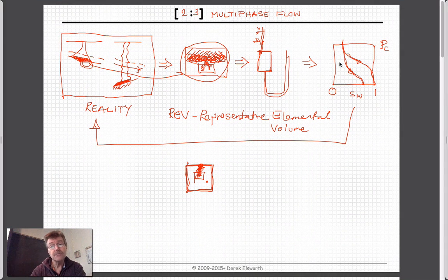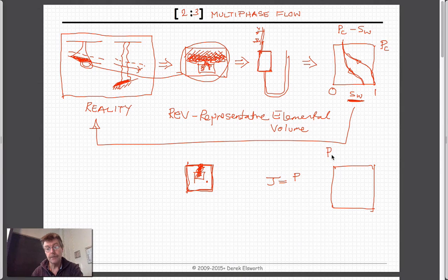So since this represents these behaviors, it seems reasonable to think that if we have this information in a capillary pressure versus saturation curve, then we should be able to use that, maybe, if we know what this is, to say something about what happens in situ. And the final part that puts this together is that we can also scale this in a certain way, very important, to these Leverett curves, which give us the capillary pressure, which I suppose we might define as always the difference between the non-wetting fluid pressure and the wetting fluid pressure.